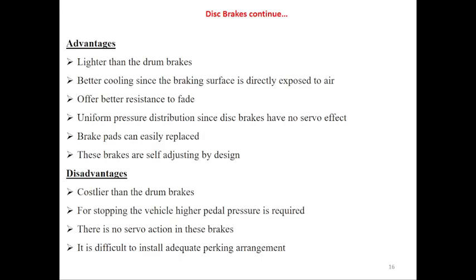Then it offers better resistance to brake fade. Then uniform pressure distribution, since the disc brake has no servo effect. Then the brake pad is easily replaced. Then the brakes are self-adjusted by design.